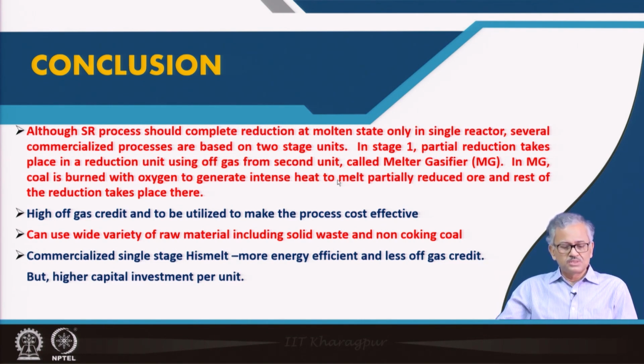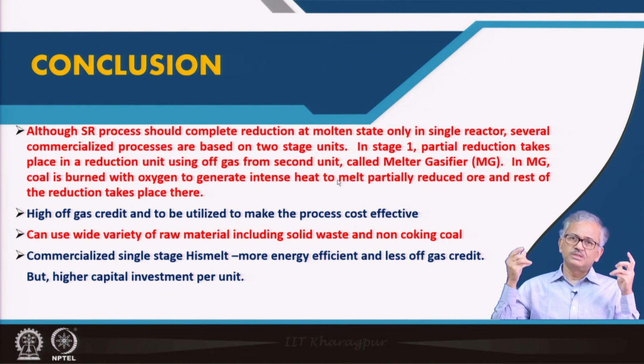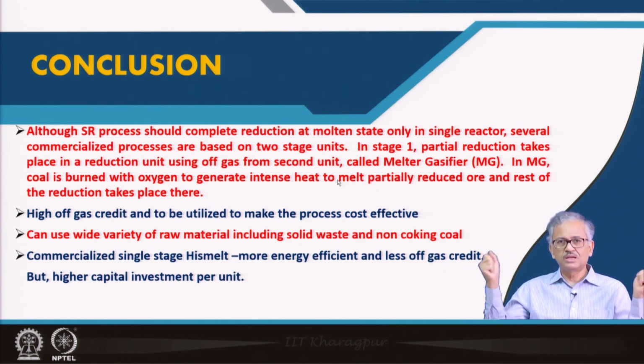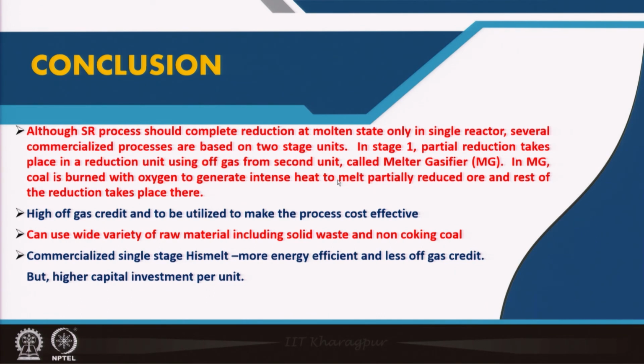But the most popularized processes are the Corex process as well as the Finex process. The Corex process is most popular, and it is basically a two-stage process, because if you want to use iron ore, lumpy ore or pellets, then the two-stage process is better. If I want to directly use the iron bearing waste, iron ore fines and all this, then the single stage process can go. We have iron ore deposits in India, so we have the availability of lumpy ore, little low grade iron ore lumpy ores. In that case we can go for the Corex process. That's why the Corex process has come.